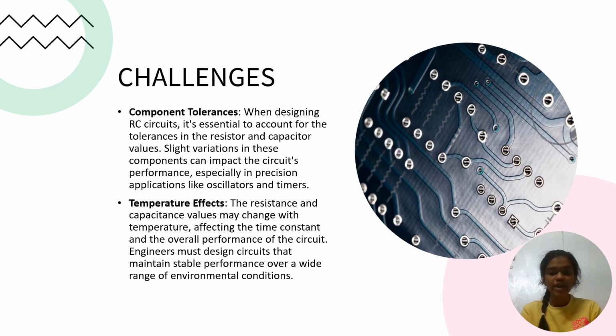What are the challenges faced using these RC circuits? Component tolerances. When designing RC circuits, it's essential to account for the tolerances in resistor and capacitor values. Slight variations in these components can impact the circuit's performance, especially in precision applications like oscillators and timers. Even a small change in the resistance and capacitor values will cause a variation in precision. Then applications like oscillators and timers which work on these values will be impacted.